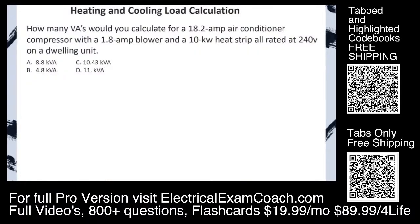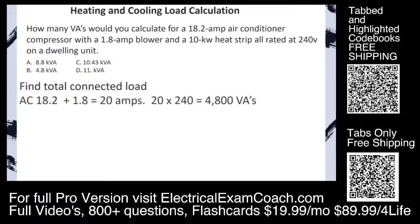How many VAs would you calculate for an 18.2 amp air conditioner compressor with a 1.8 amp blower and a 10 kW heat strip rated 240 on a dwelling unit? First thing we're going to do is find our total connected load. Let's do our air conditioning first. We take our 18.2 amps and then we add it with the blower motor. That's going to give us 20 amps.